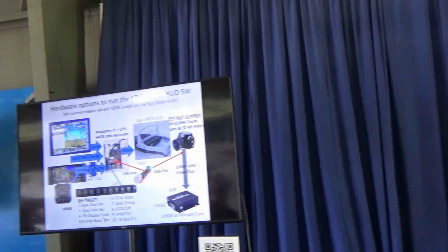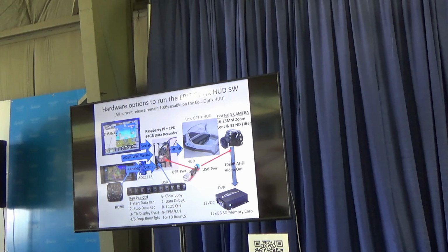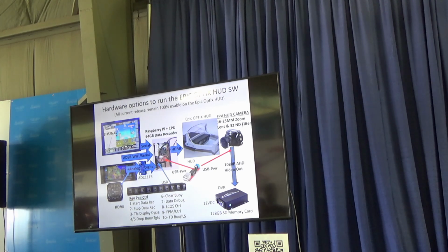Button number 7 brings up a series of displays with all the digital data being processed by your Raspberry Pi. And it's amazing the amount of data that little bugger is going through when it's pulling in ADS-B traffic, maybe 100 miles away when you're up in the sky, and then it's digitally figuring out exactly where your aircraft is and then where each of the ADS-B targets are, and doing it in such a way that you can track down.